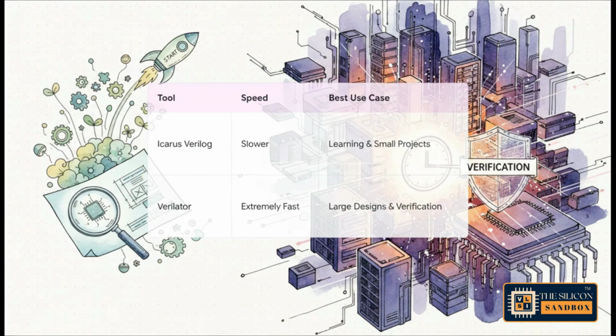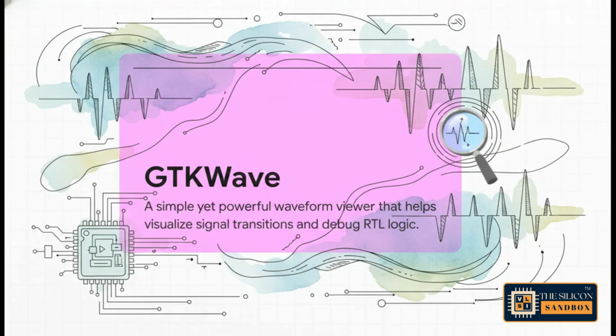So really, the choice is pretty simple. If you're learning or you're working on smaller projects, Icarus Verilog is your best friend. It's easy to use, does the job. But when you need to verify a massive design and every second counts, Verilator is the undisputed champ. No contest.